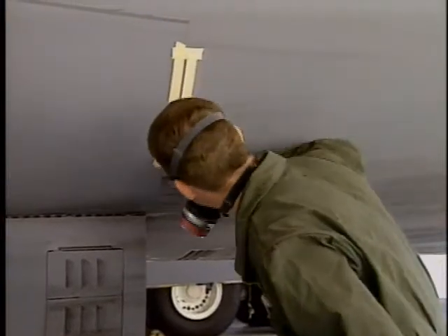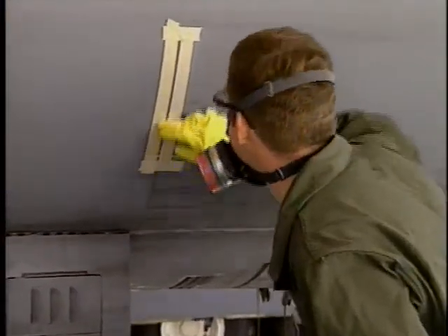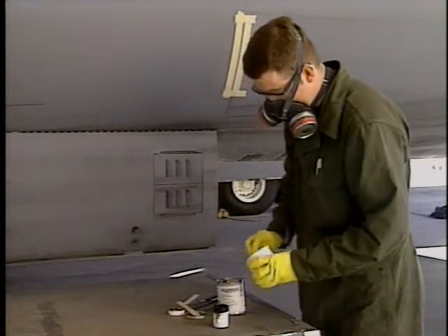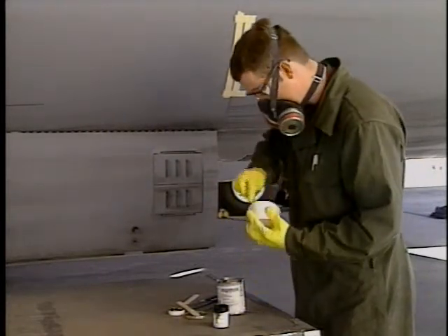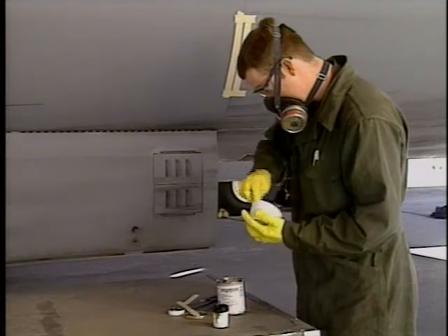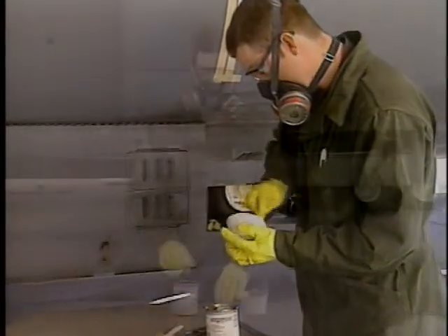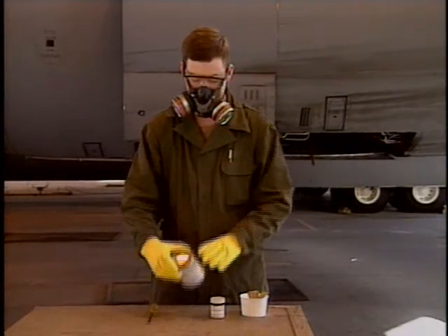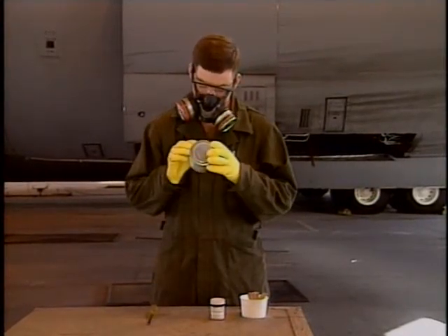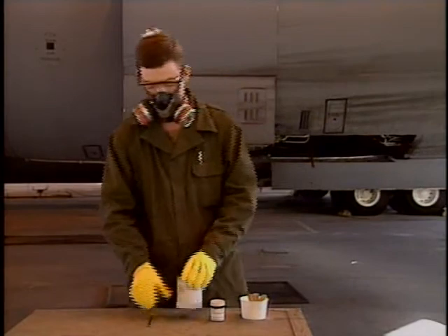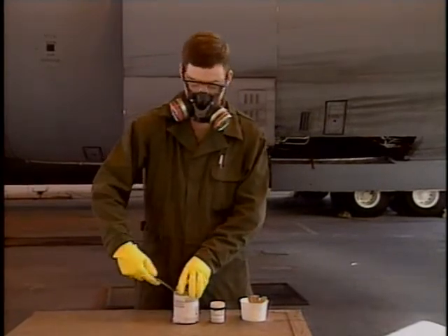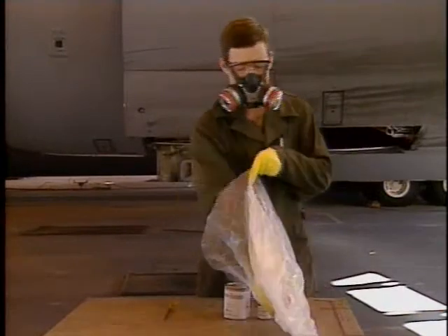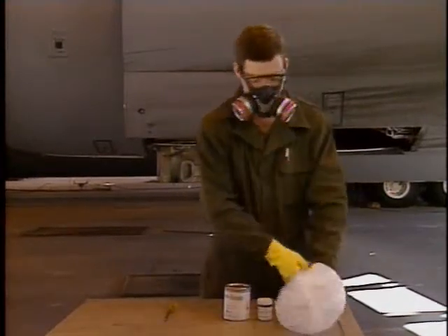Areas that require sealant also require special attention. Thoroughly prepare the surface before applying the new sealant. Correct mixing of the components is essential for proper curing and adhesion. Always check the shelf life listed on the label. There have been many cases where the products have failed or didn't provide the desired effects because the shelf life dates had expired.